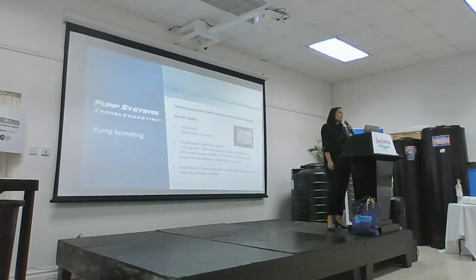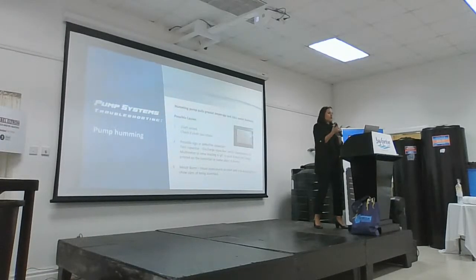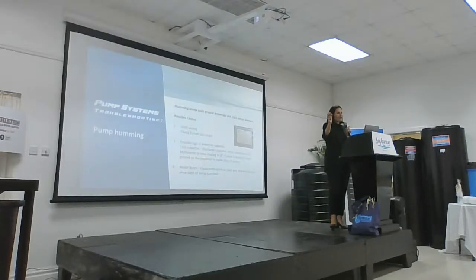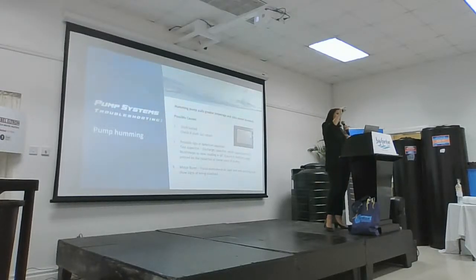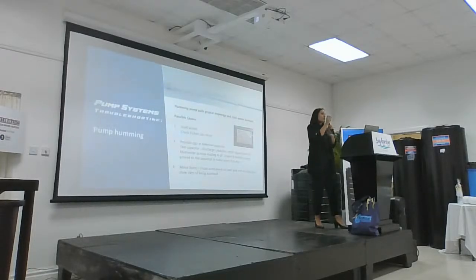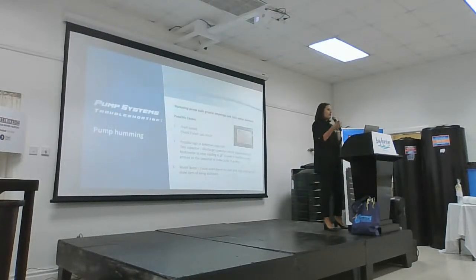Another reason why your pump may be humming is your capacitor. So you want to test your capacitor. You're going to test the capacitance and measure it against both the rating on the nameplate as well as the rating on the actual capacitor itself. You want to ensure that the capacitor reading matches exactly what is stated on the plate, to ensure that your capacitor is good and functioning properly.